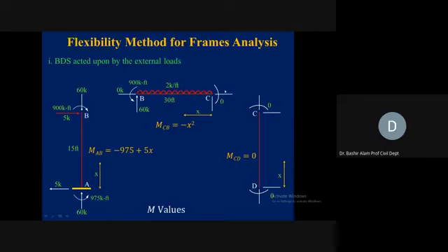Here I can give you the example of BC. If we take the BC, this vertical is 0. So here the moment equation will simply be 2 times x squared divided by 2. But if we write from B to C, taking B as origin, this will become 60 times x minus 900 minus 2 times x squared divided by 2. So it will have 3 components, while from here it has 1 component. So it is easier to take C as origin instead of B as origin.